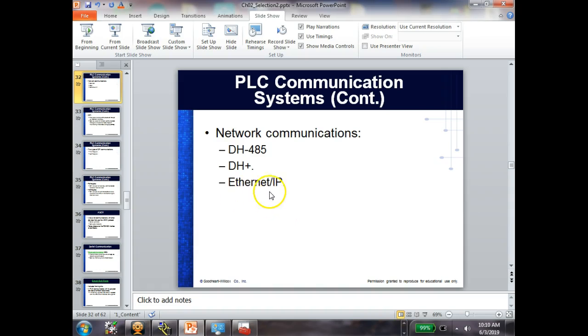Well, I'm sorry, it supports Ethernet IP because it's got the network connector on the side, but it doesn't support the DH485. So what do I have? Yeah, I got this converter right here. It takes me from standard USB over to this DH485 or the RS-232 connector. Make sense?